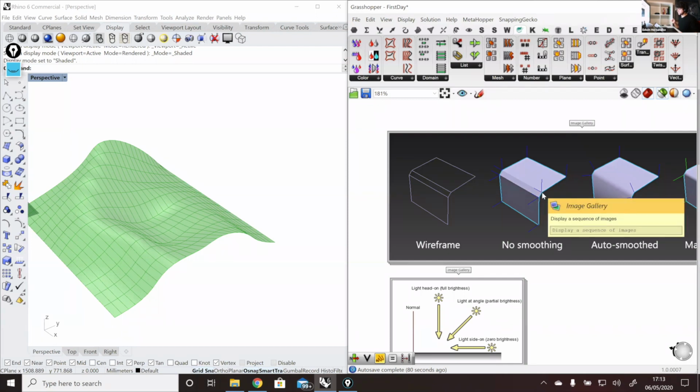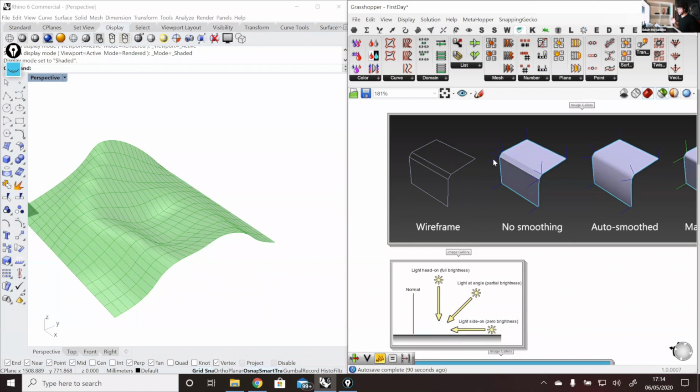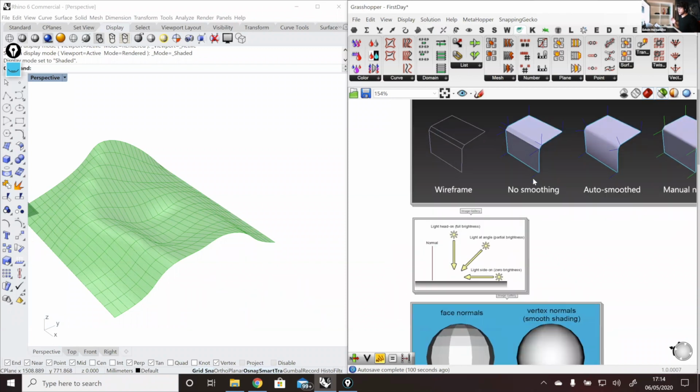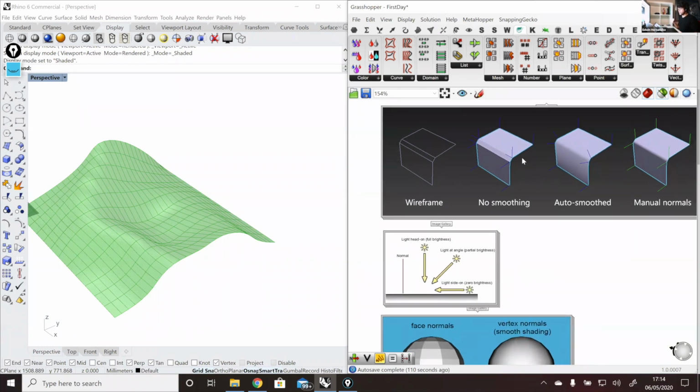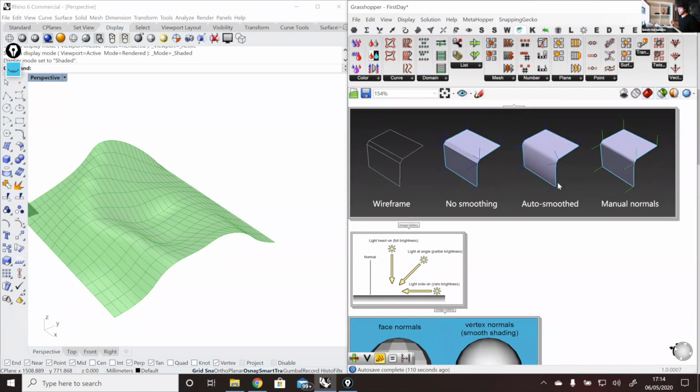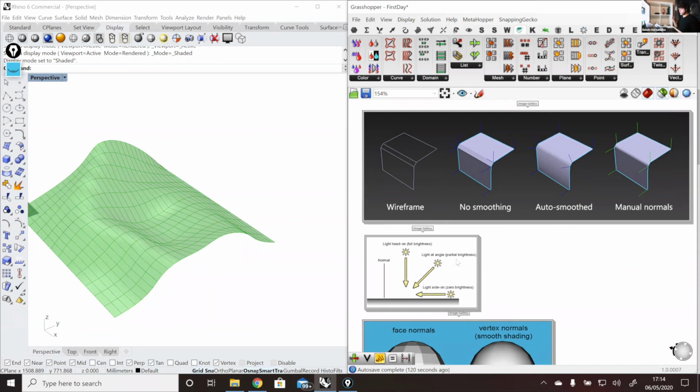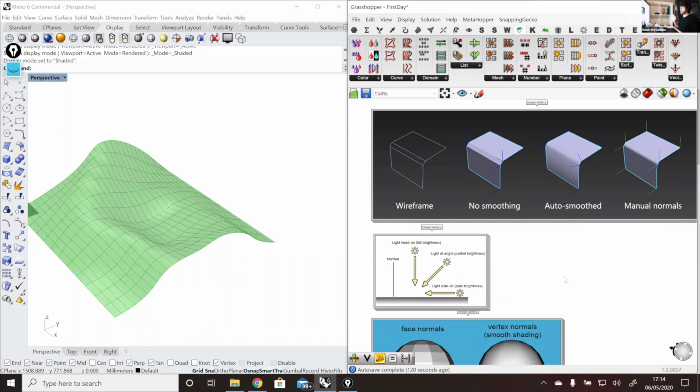What happens is that if we see here, this one actually has 2 normals in each of these vertices. So each vertex contains 2 normals. Therefore, if we check here, our light reflects in different directions across our mesh, depending on the normal direction. Because we have different directions, we can see a seam in our mesh. However, if we weld it, that means we are joining our normals into one single one. Then we have just one single normal in each vertex, and therefore our light is reflecting in the same way, and it simulates that our mesh is smooth.